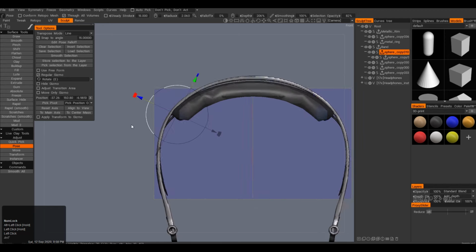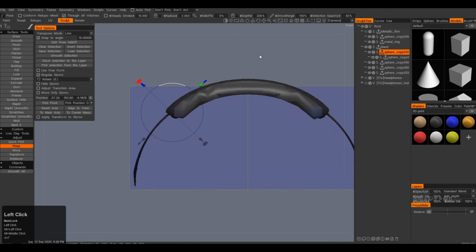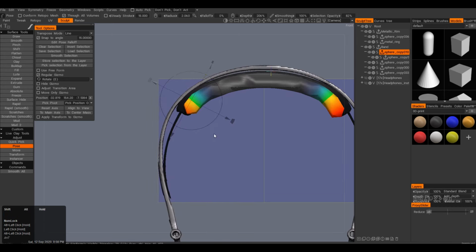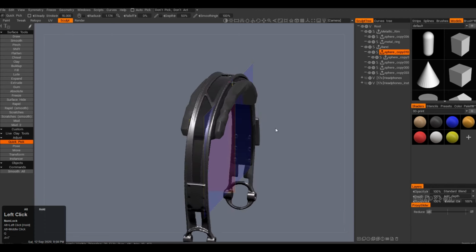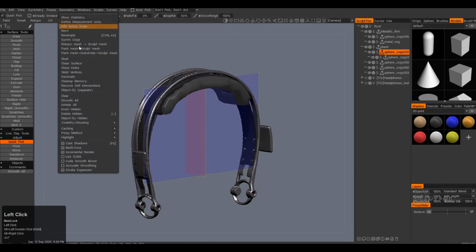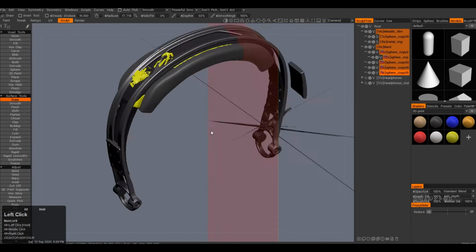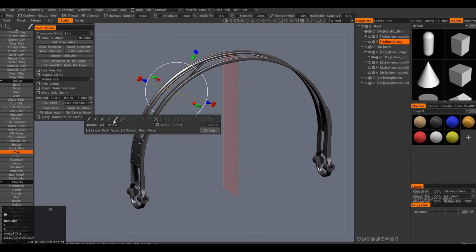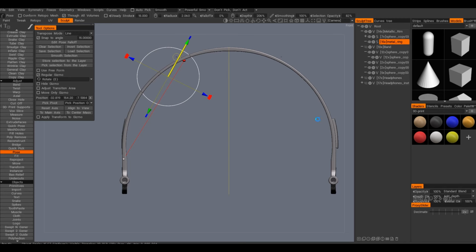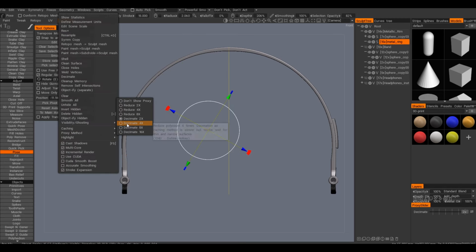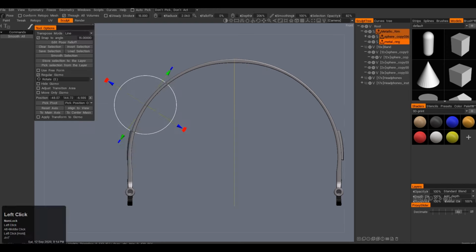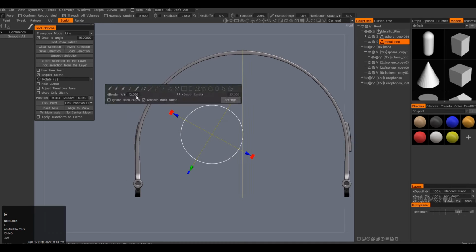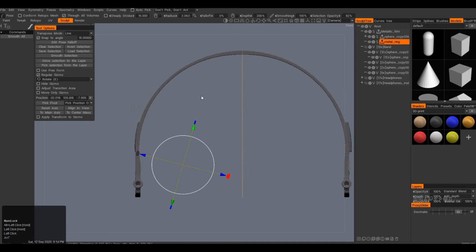Also with these proxies, you're not always sure if it's going to look okay when you unproxy it. So here I did a super heavy proxy, and I can see how it's all really blocky. So that wasn't the ideal way to do it. You can see here now, I did the unproxy and it was all screwed up pretty badly. The proxy was like 8x proxy. It was decimating it way too much. So now this one is maybe like 4x or 3x proxy, so it's not as destructive as the stuff I was using before.